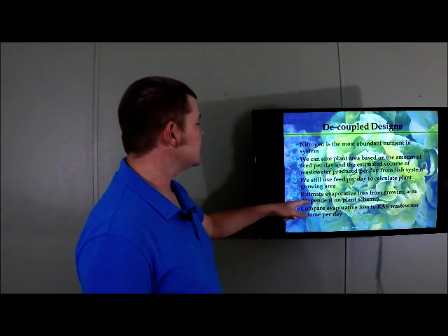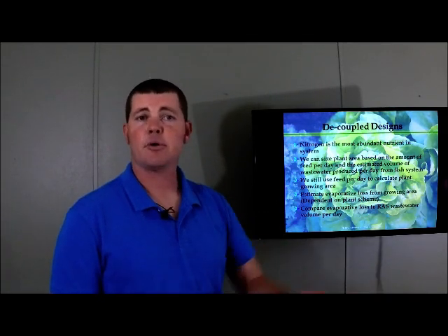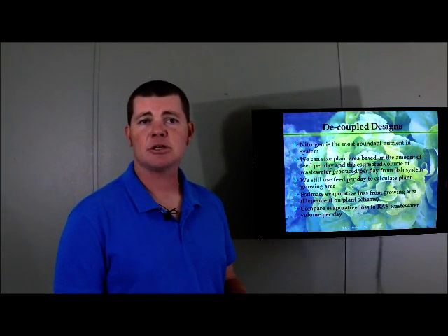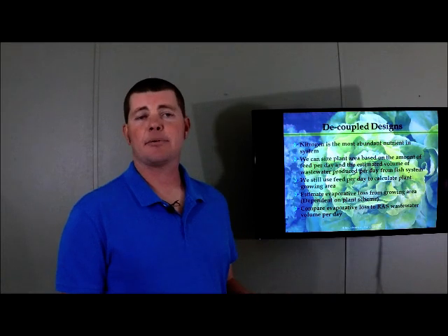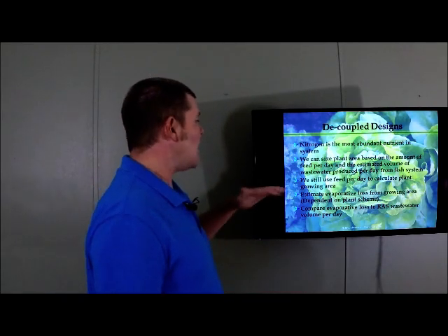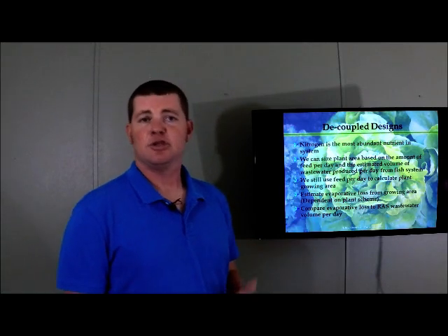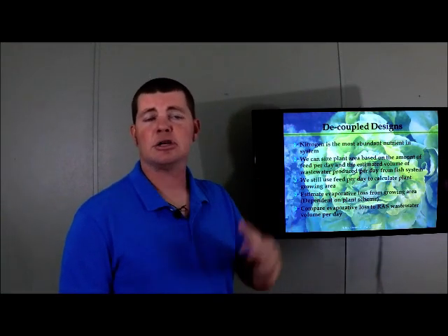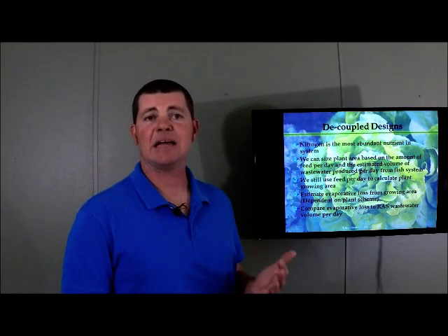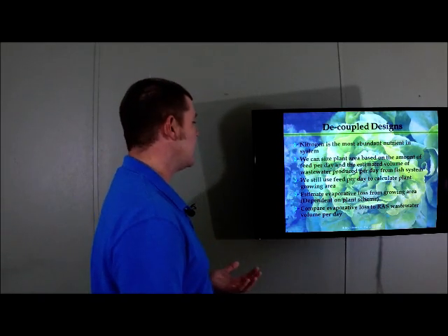But what I would say is stick to the feed rate per growing area, and it's already very, very closely matched to the actual evaporation that's going to happen in a typical greenhouse scenario. So I would go off of that and then do a little alteration on the back end, but it's much easier to just size off of the feed input, okay?